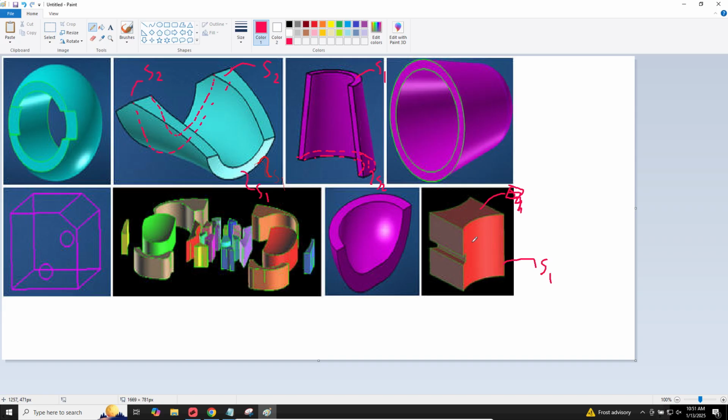This is the first face here. Then we can go in this direction to this opposing face, S2. And now this will work. So let's go ahead and draw a checkbox here. As long as you create these scenarios, these cells where side 1 is similar to side 2, then you can create the hex mesh.